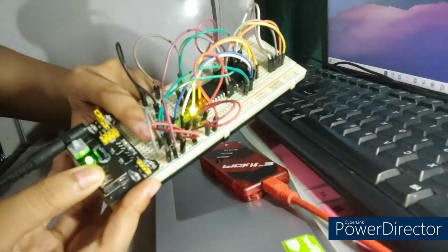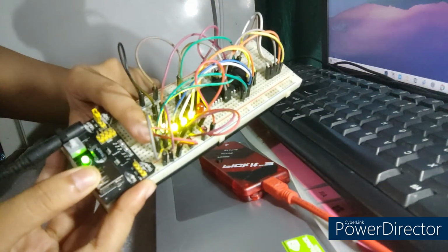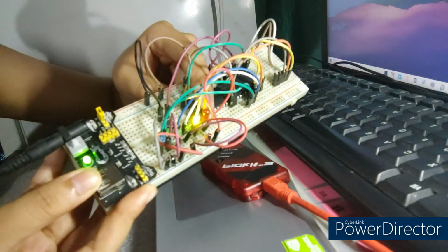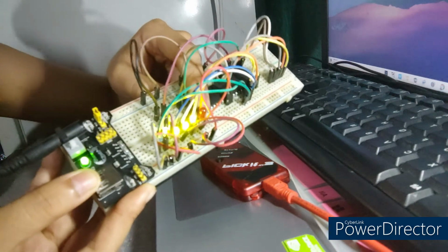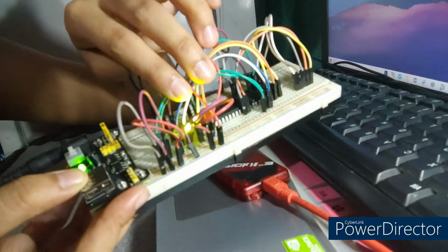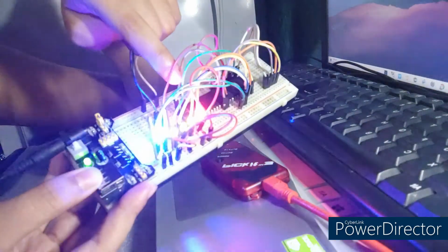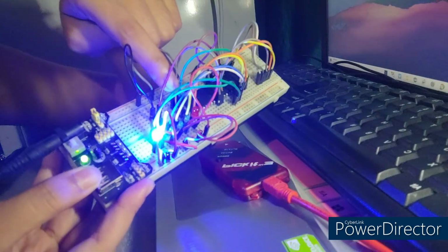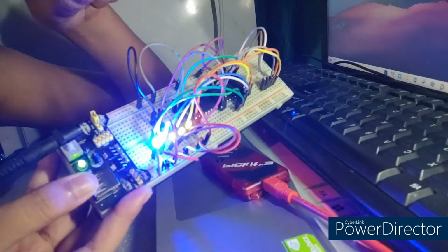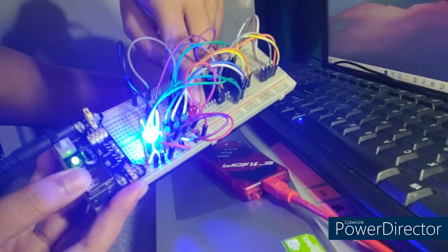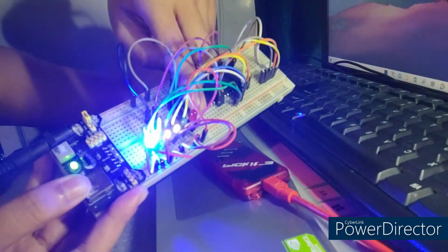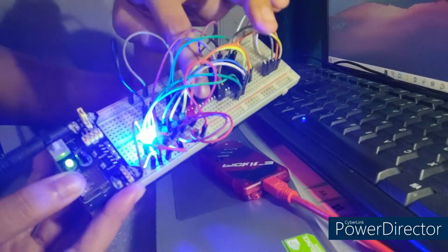So this is a nice practical application for our pedestrians, wherein the red LED will be our indicator, which will allow the pedestrians to know if it is already safe or not safe to cross the lane. And our 4 green LEDs here will be our time duration. Okay, the persons are given 2 signals that will let them know if it is safe or not safe to cross the lane. So the first red blink here will be the signal that it is now safe to cross the lane, and the second blink of the red